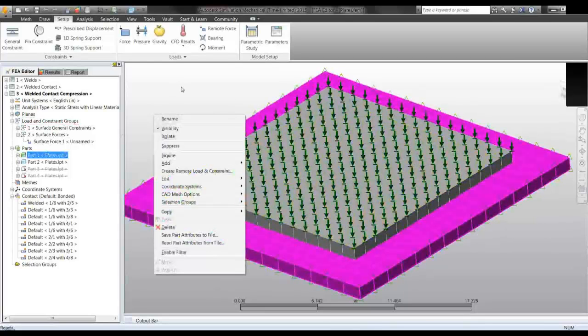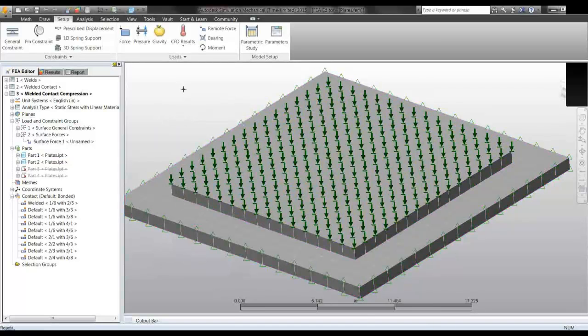If we wanted to assess the reaction forces between parts, then we could take advantage of the reaction force calculator. By default, the reactions between elements end up being 0 because each element has an equal and opposite reaction force to each other, such that when we're looking at the reaction forces, we see them at our applied loads and also at our boundary conditions.